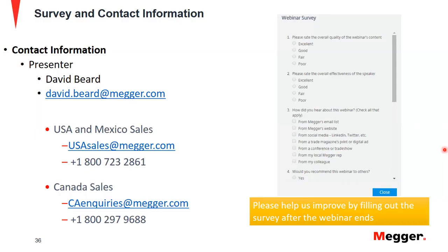Beautiful, thank you. Mohit, I have a question for you. Can overcurrent elements misoperate for faults not on the protected line? Yeah, absolutely, especially on radial feeders. I'm assuming the question relates to non-directional overcurrent elements.